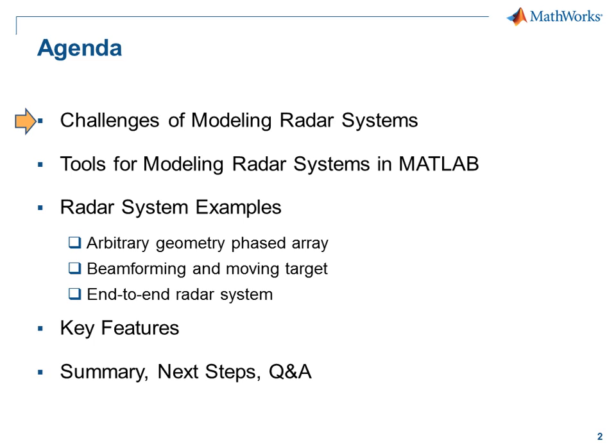First, we'll model a phased array antenna with a complex geometry. Then we'll see a beamformer example where an array is mounted on a vehicle and needs to track a moving target. And for the third example, we'll model a complete end-to-end radar system.